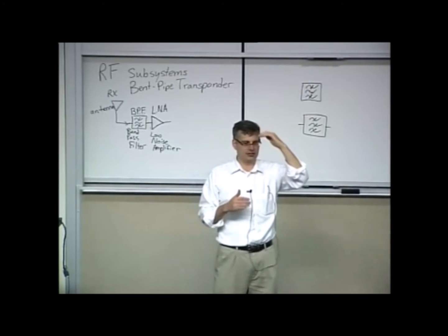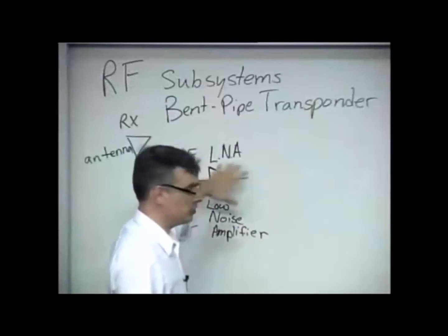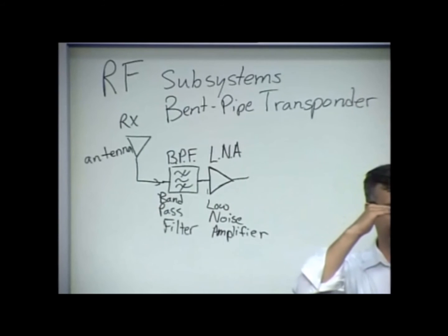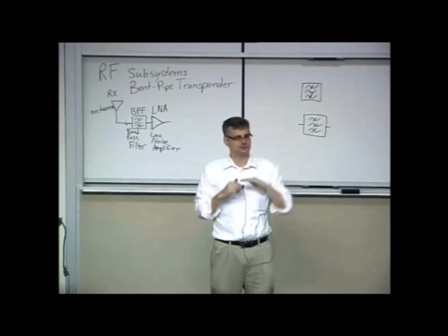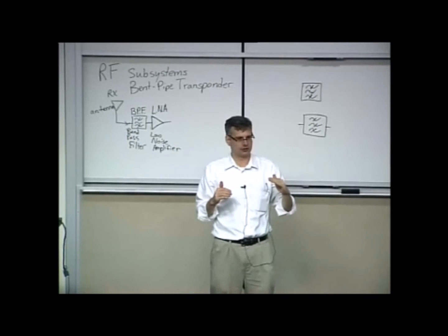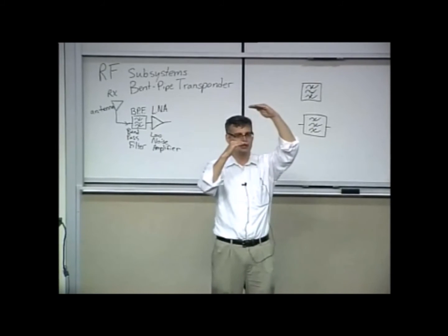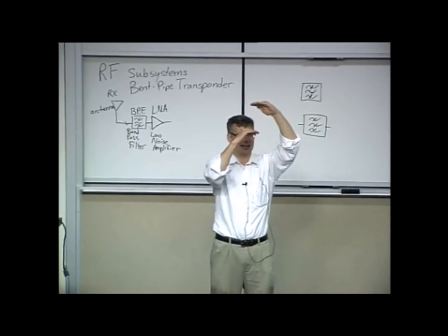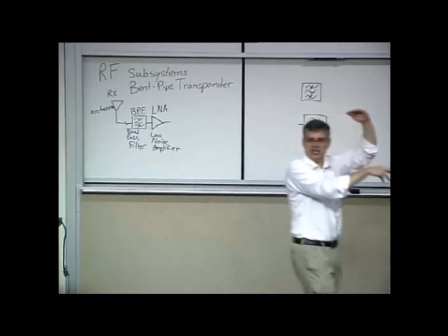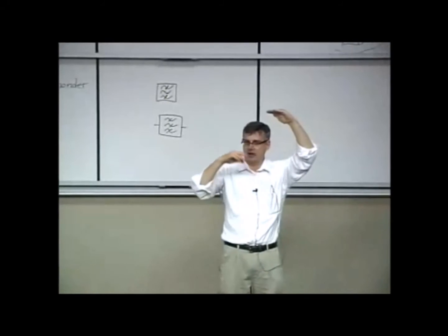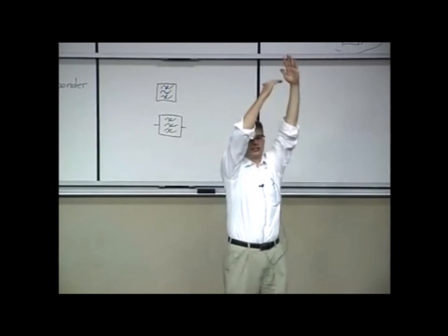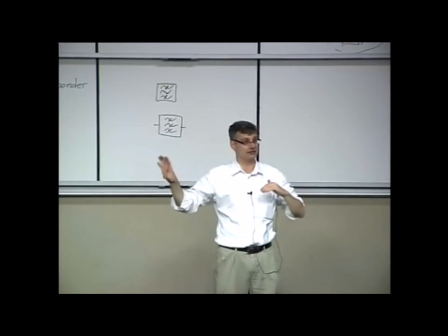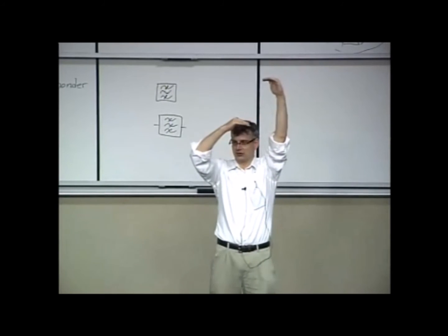Because whatever noise comes in at this point, you're amplifying from here on out. So I've got signal, I've got noise, and I'm amplifying them both when I run them through that. Well, I would much rather amplify a little bit and add very little extra noise at that point. And then in subsequent stages, I can buy cheaper, higher gain amplifiers that raise everything up a lot more. Those can add a lot more noise into the system relative to the first amplifier, because you've already got a strong signal at that point.